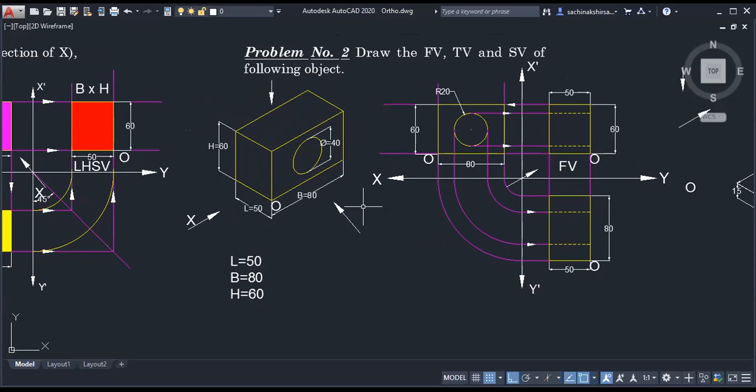And with the circle, a white dotted line came. In which view did the dotted line come? In the front view and in the top view, a dotted line came. What does this dotted line indicate? The circle is on the left-hand side, invisible in the front view direction, and we cannot observe it in the front view or in the top view. That's why it looks dotted. That's why that dotted line came. Correct? Shall we go next?